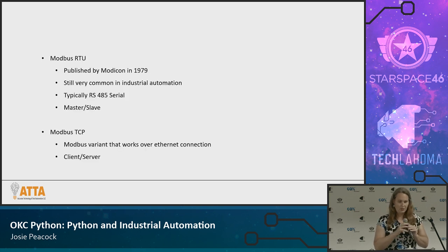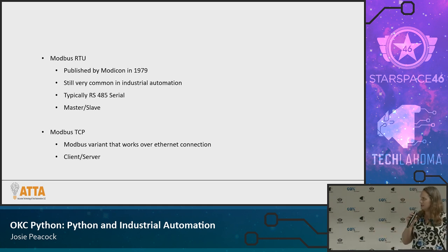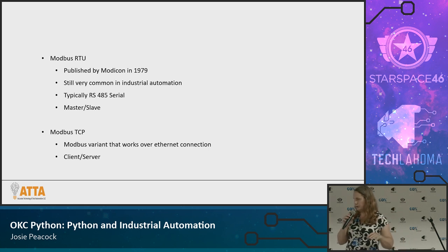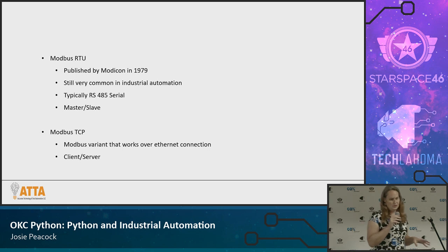Boy, I didn't do that right at all. Now, a second one, where we go back in time: Modbus RTU and Modbus TCP. Modbus is a protocol that was developed by Modicon in 1979, which is probably older than a lot of people here. You'll see this a lot, like when we use a smart meter for kilowatts, volts, and amps, which you communicate with directly using RS-485 Modbus RTU.